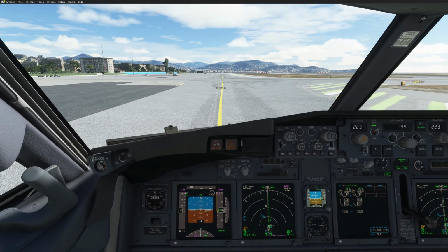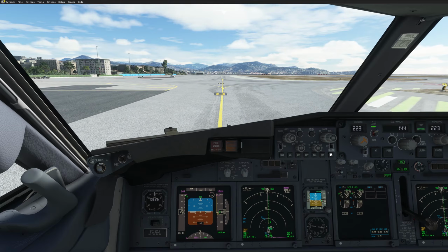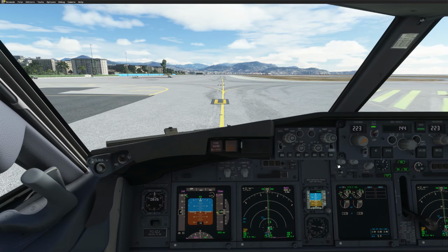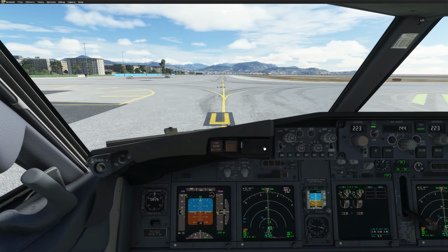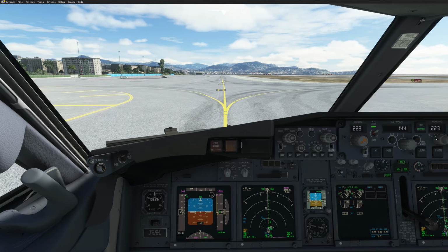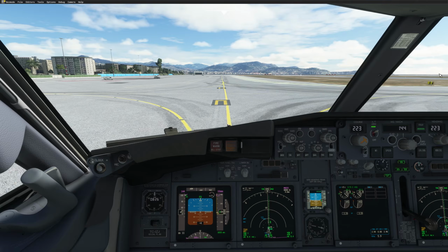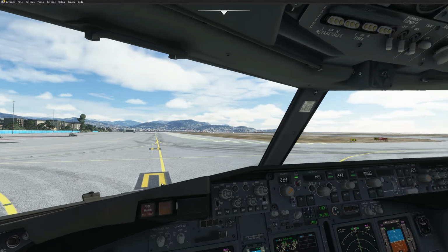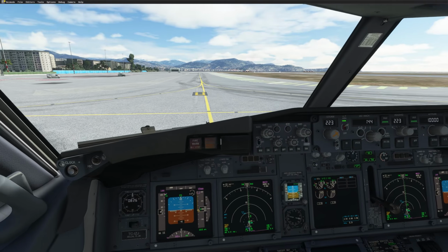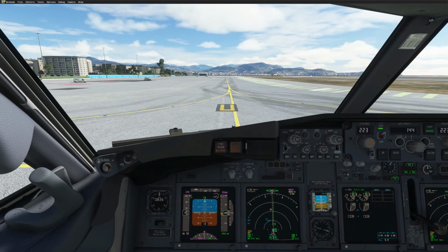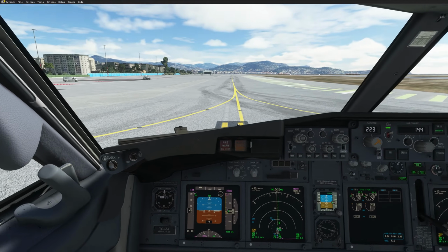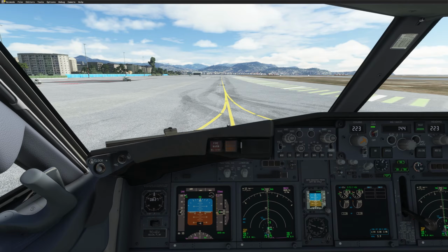Should we continue the takeoff, my call will be continue. No actions below 400 feet, except positive rate, gear up, cancel any warning, any lights. At 400 feet, I will ask you to select heading to the left over the sea. We are safe, we climb to 3000 feet, and please start APU and inform ATC. Any questions? So that will be a standard review of our takeoff briefing.